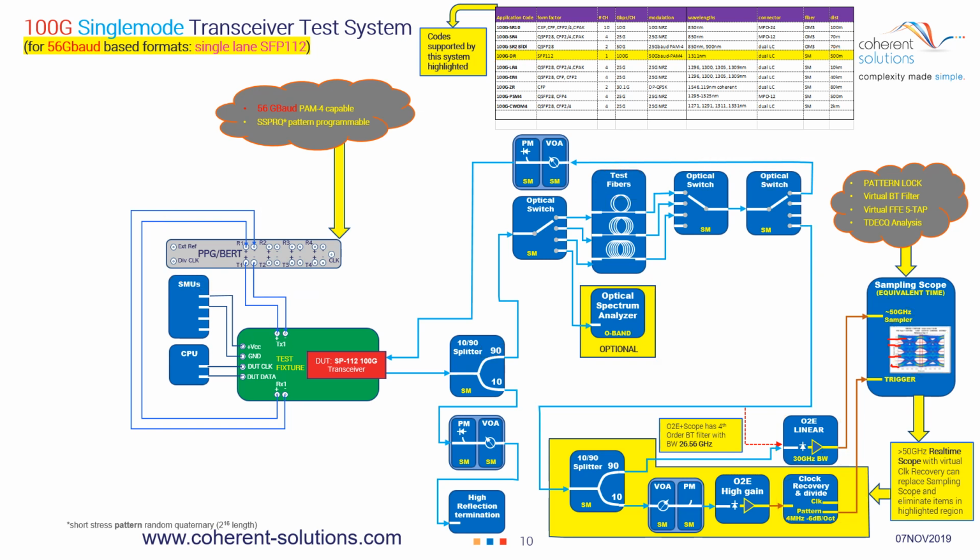Please note, in this case, we were actually working with a standard known as PAM4. As we mentioned earlier, that means there are 4 distinct levels in the optical signal. The requirements for the O/E converter and the filtering are slightly different than the traditional NRZ. I won't go into too much depth, but let me just say that most of the filtering in modern oscilloscopes today is handled through digital signal processing.